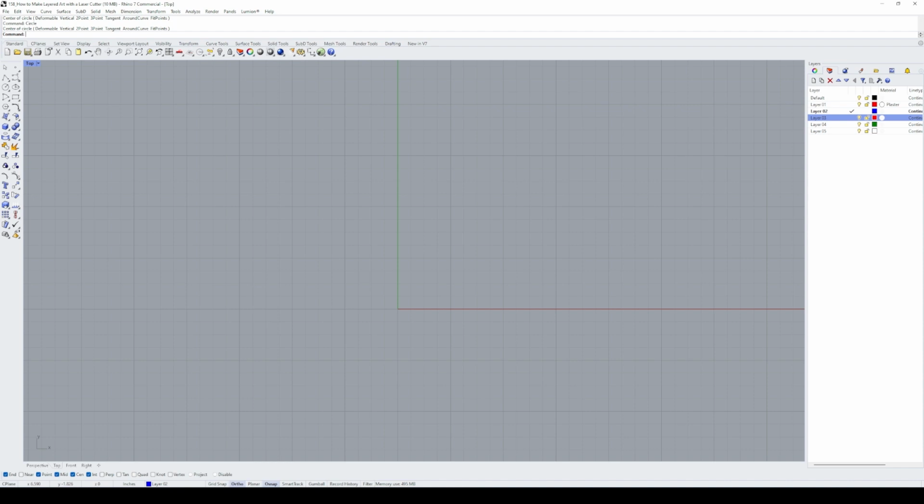To design this project, I use a software called Rhinoceros, which I use for all of my craft projects. If you don't have it, you can look for any other CAD software which will have the same process, commands, and workflow. First, we draw a line and copy it to have 8 points of symmetry. In Rhinoceros, there's a command called polar array where you can tell it that you want 8 duplicates equally spaced over 360 degrees.